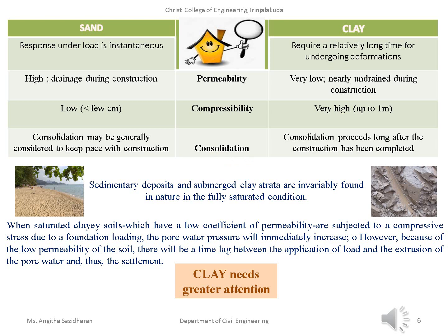And now about consolidation. What is the difference with sand and clay? Consolidation may be generally considered to keep pace with the construction. That means if you are talking about a construction over a sandy soil, then the consolidation may happen during the construction stage itself, and the building will not be affected much. The consolidation will be over by the time the construction ends.